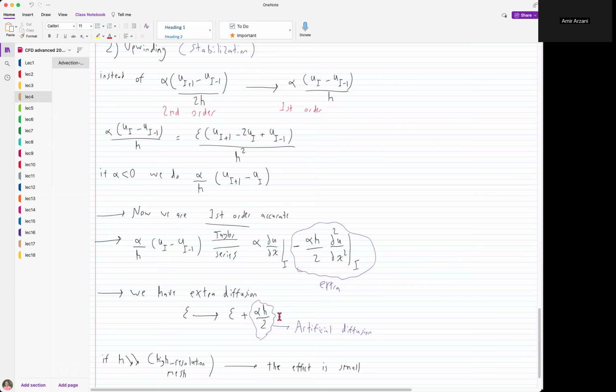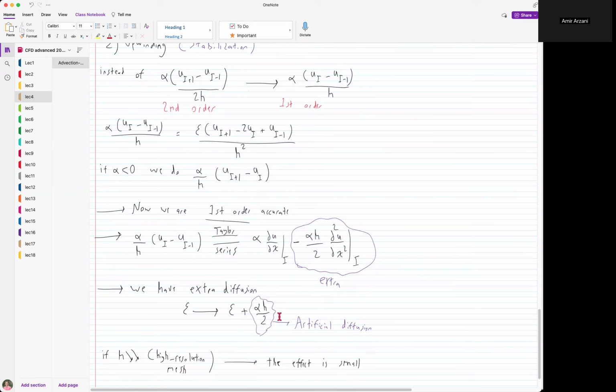Those free parameters often are grid dependent, so they're usually functions of the grid Peclet number, or if you have a time-dependent problem, maybe a function of the time step. So you find those forms, or you hypothesize and do your numerical tests in 1D, you tune them to get exact values, and then you use those stabilization parameters in the more challenging multidimensional case. Okay, so we will be talking more about this in the next lectures.